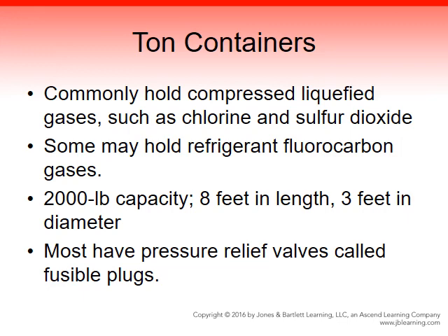Ton containers commonly hold compressed liquefied gases such as chlorine and sulfur dioxide. Some may hold refrigerant like fluorocarbon gases. They traditionally have a 2,000 pound capacity and they are 8 feet in length and 3 feet in diameter. Most have a pressure relief valve called a fusible plug.